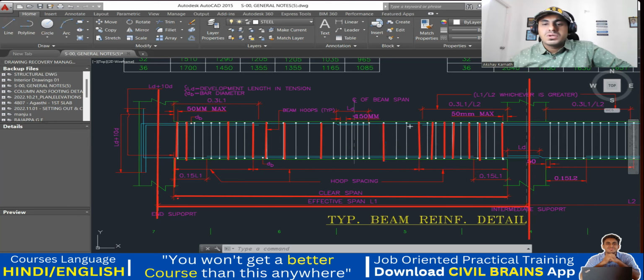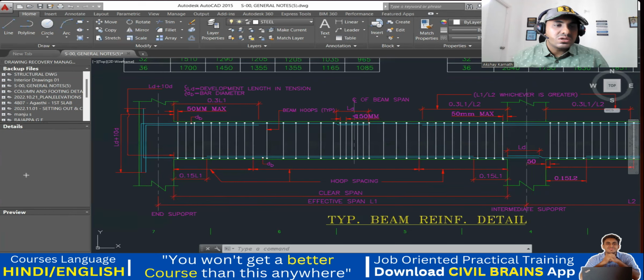Now, I told you that when it came to the lapping part in the beam, for the top reinforcement, you should do the lapping at the center. And for the bottom, near the support, within L by 4, you can do. Now, same thing you can see. I'll remove everything now. See here, he's showing something. What is that? Exactly, this is lapping.